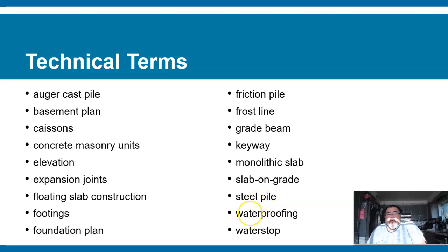Waterproofing is different. It's like roofing, except it's now basically weatherproofing material that keeps water from getting into or under the foundation or through a wall. Especially when a wall is holding up the side of a hill. That hill might be exposed to a lot of moisture that runs downhill, and your building is up against the side of the hill. You would put waterproofing and then some form of drainage so that water doesn't collect along or underground along the building, on that high side of the building.